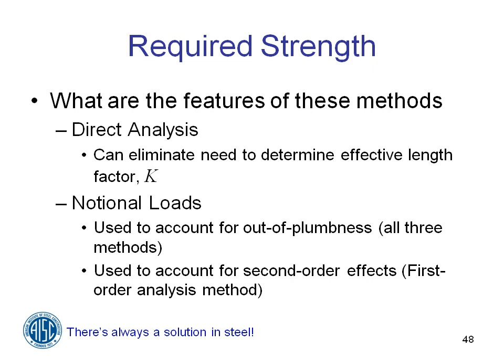So the features of these methods, the key for the direct analysis method is that it eliminates the need to determine an effective length factor. Now, if we were talking about the full day seminar on stability analysis and design, we would spend a good bit of time showing why it's important to eliminate the effective length factor because of all the uncertainties in how to actually get a correct value. So it's really a big step forward to be able to do an analysis and not have to use the effective length factor in the design of your compression members.